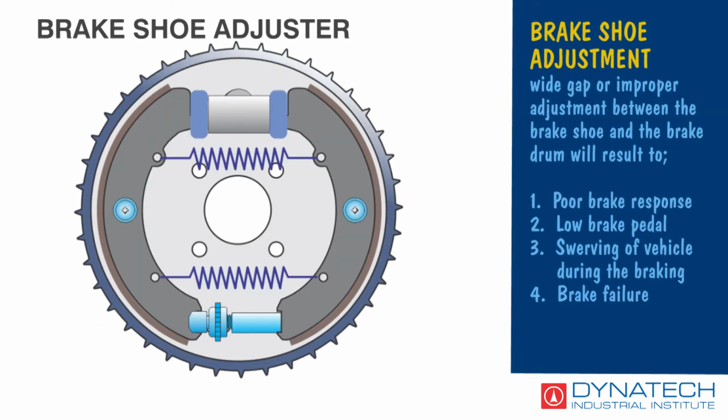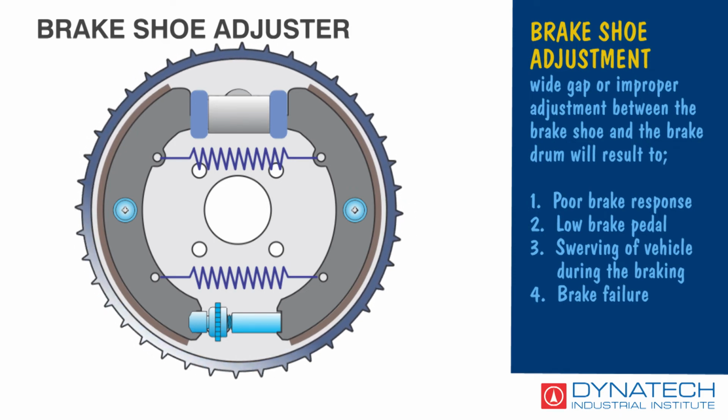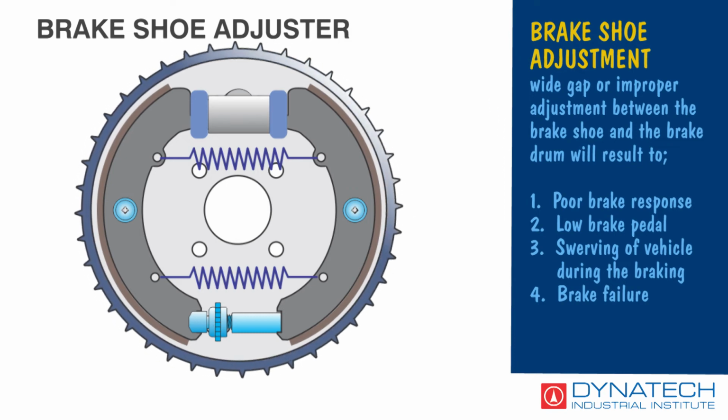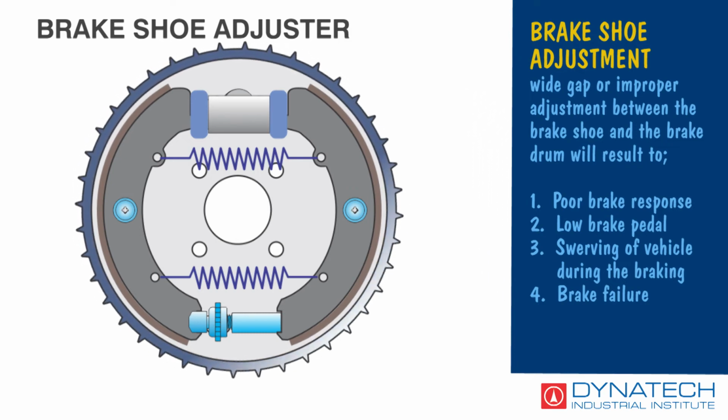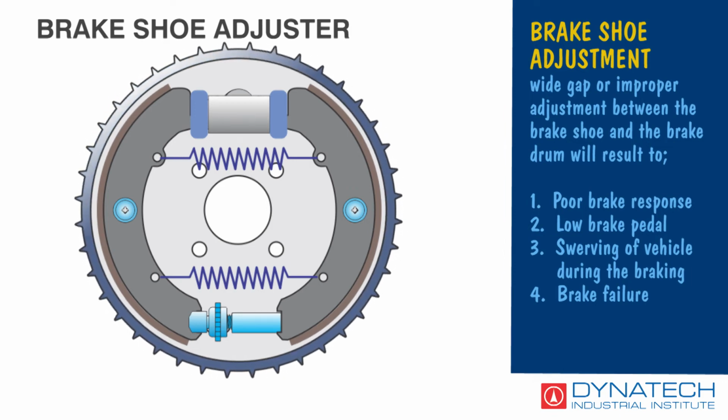Wide gap or improper adjustment between the brake shoe and the brake drum will result in: 1. Poor brake response, 2. Low brake pedal, 3. Swerving of the vehicle during braking, and 4. Brake failure.